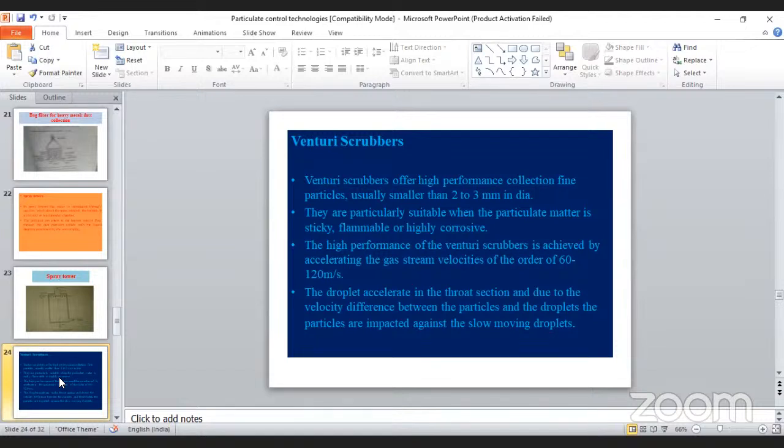Whatever the gas droplets, whatever the particles can be converted and condensed, it will be condensed. And some of the solid particles will be dissolved and solidify and settle down. That's what we are collecting, the impurities in the form of slurries in spray towers. Now you please tell me, spray towers are also used to settle down the particles through the water spray, and scrubbing technology also works on the same concept.